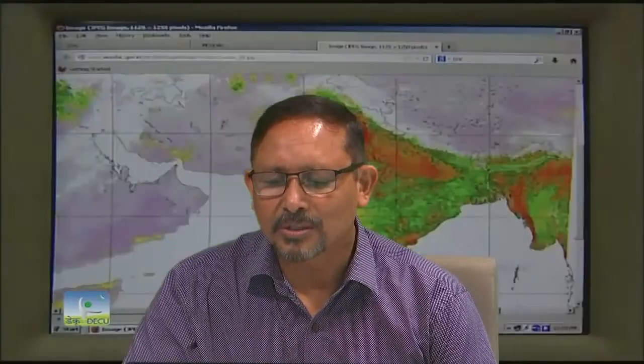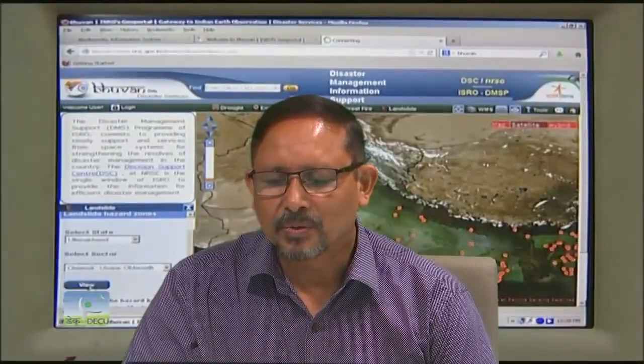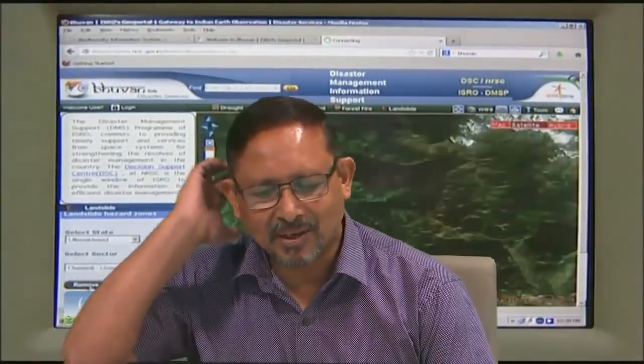On what basis is the threshold value given, and how is stream ordering given? I just explained the threshold value. When we prepare the flow accumulation map, the map shows numbers, and the number shows how many pixels this pixel receives water from.